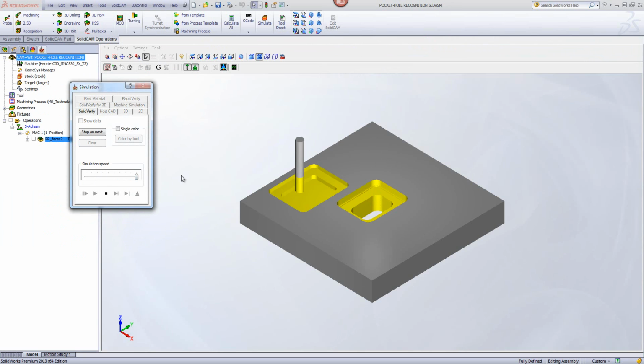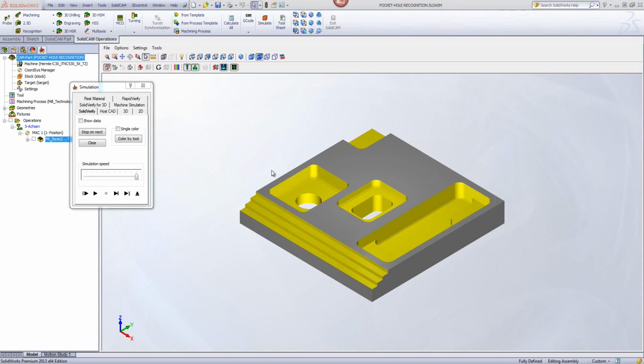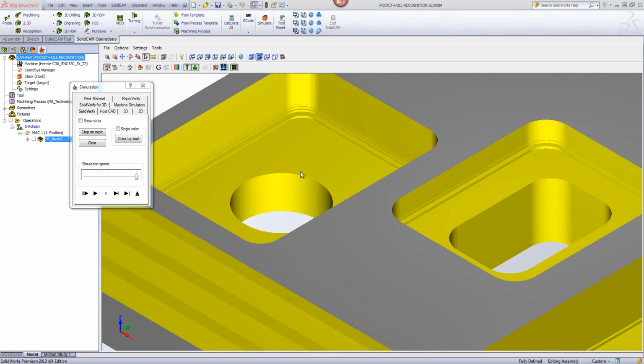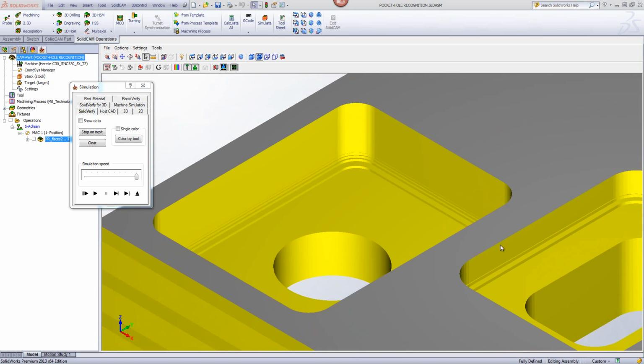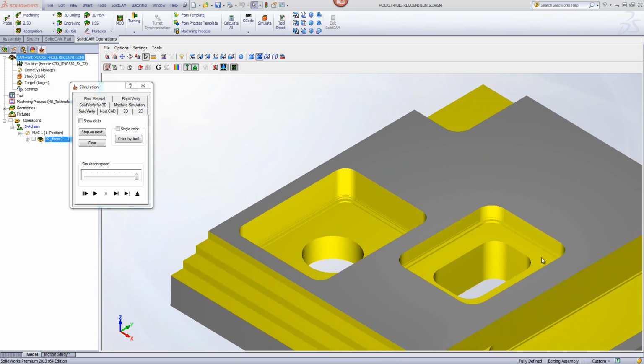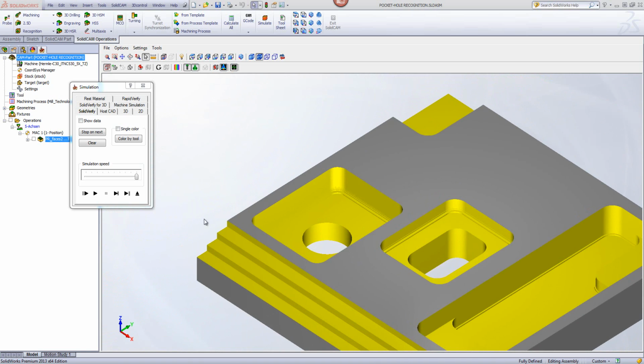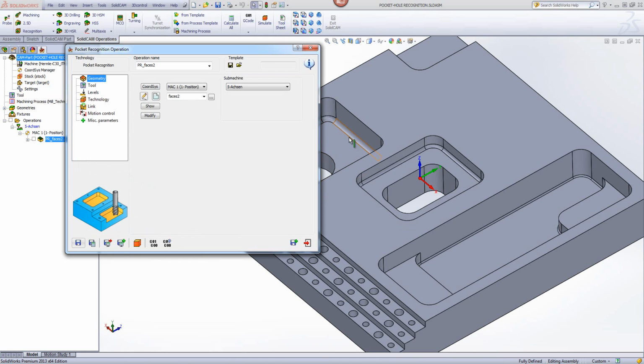Run our simulation. And note now we have this down here at 4 separate steps. 1, 2, 3, 4 separate steps. Here we have it at 2 steps, and the 1 millimeter, we have it at 1 step. Of course, I could have broken it down. I could have written down as many steps as I wanted over there. So I can get this actually pretty smooth down until it's actually what I would like to have for a fillet, for a bullnose tool to finish that off.